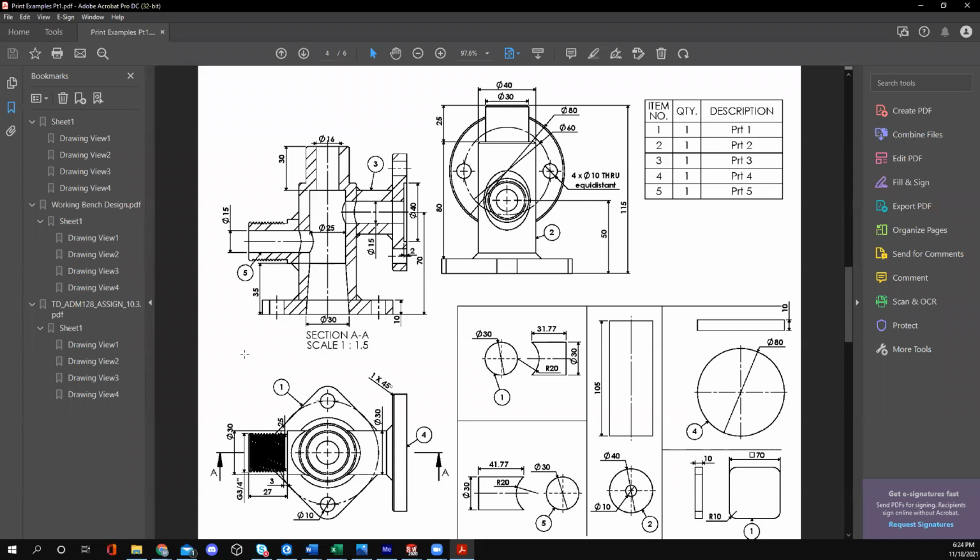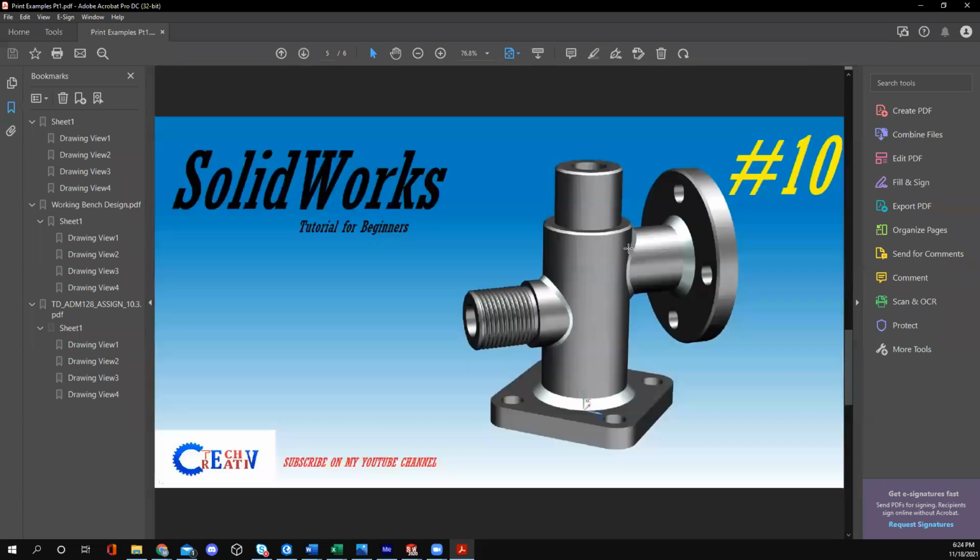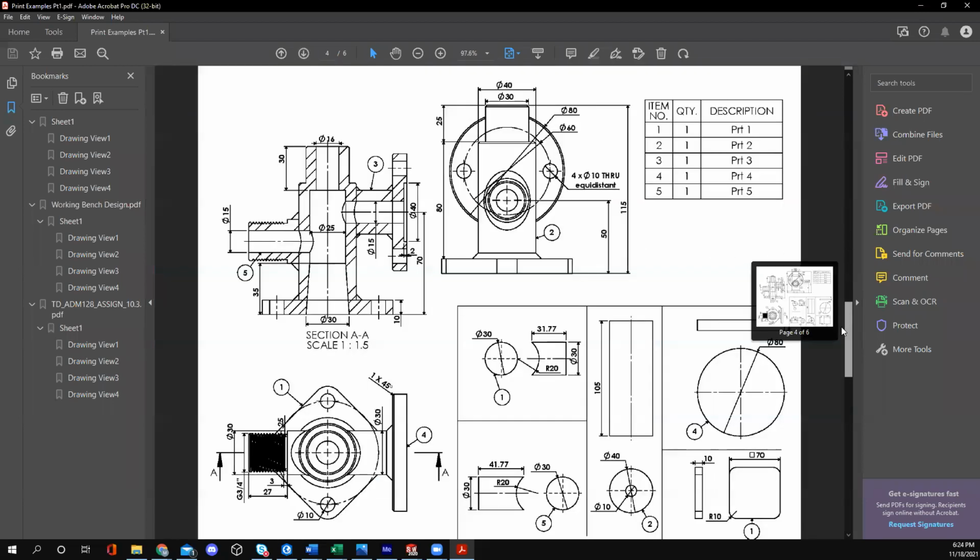I think that this would probably be, let me see, I scrolled down, assuming that there was a bottom part to that page. There isn't. I would assume it's just a standard weld that they're requiring for each one of these, like a certain size bead. I don't see an actual weld call out on any of these either. So it's just all pipe dimensions, whether it's machining or stock pieces, and then you know what your cuts need to be so that they mount well together. And then it shows the weld beads, but it doesn't actually have the call outs for the weld beads.